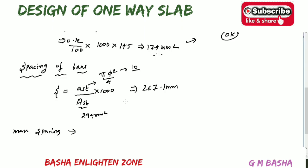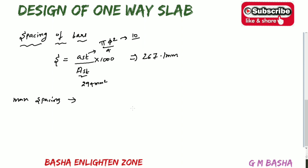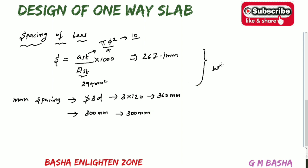So we already calculated the spacing here. The next condition is that it shall not be more than 3 times the effective depth, and the second condition is 300 mm. Three times the effective depth of 120 is 360 mm, and the third value is 300 mm. Out of these three, take whichever is less.